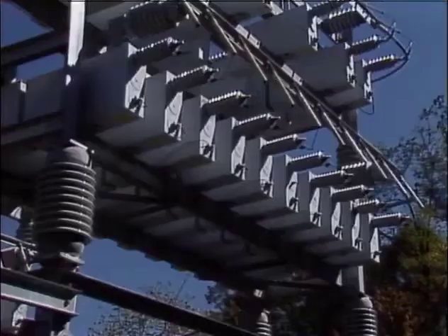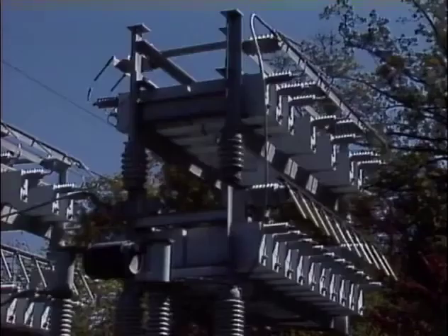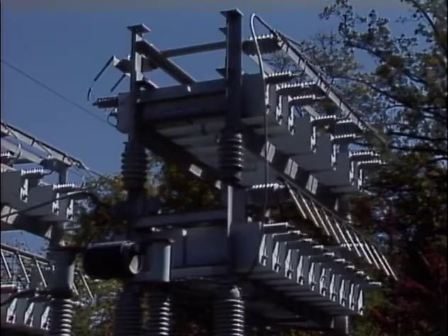Whenever a capacitor or a group of capacitors in a bank is replaced, the balance of the bank has to be checked. What this means is that the total capacitance in each phase of the capacitor bank should be equal to the total capacitance in each of the other two phases, within a tolerance specified by the manufacturer or company standards. To check the balance of a capacitor bank, measure the current of each unit in a given phase of the bank. All the currents for the phase are added together to get the total current for the phase.